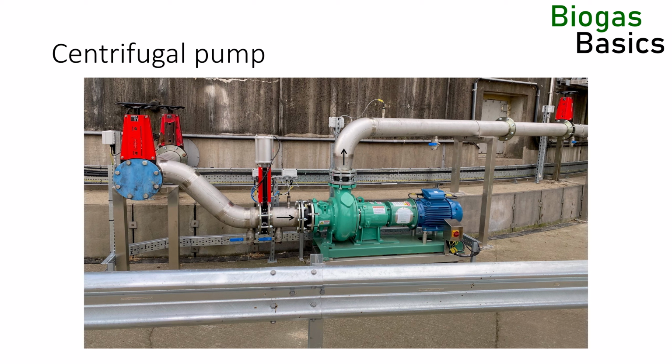Centrifugal pumps used for digestate often have special impellers, which are less efficient than impellers for gas-free fluids like water, but can deal better with gas accumulation. When using centrifugal pumps for digestate, speak to the pump supplier to select the correct impeller for this application. If pumping digestate, centrifugal pumps must be vented properly and operated with a high suction pressure and short suction lines with no high points, a recurring theme for all pumps handling digestate.